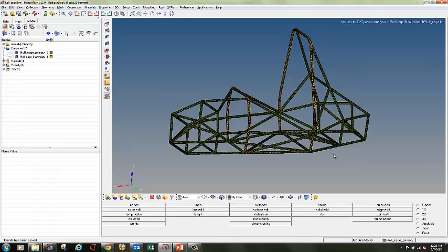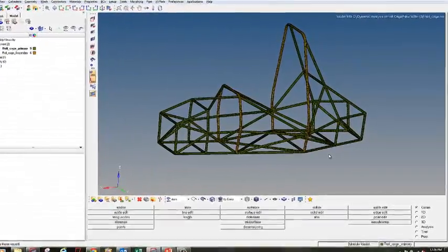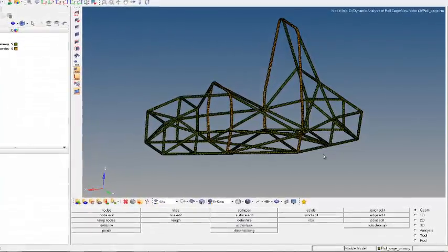The next step, after creating the material properties, meshing, and editing the mesh as per the qualities required for dynamic analysis, is to start with the solver deck creation. The first step in creating the deck for front impact dynamic analysis is to create contact.